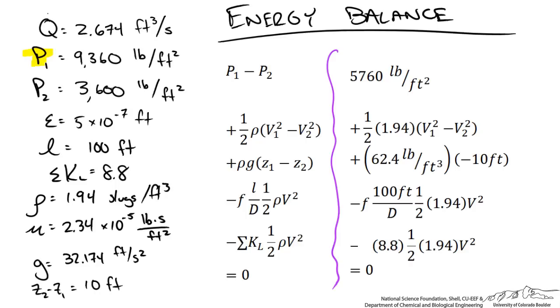Now when we think of this system, water's coming from a main water line into one we are building for the apartment complex, and eventually out of some type of faucet in the building. So the specified large diameter of the supply line is there to give us the impression that the velocity in the main line is much smaller than that in the line we are building. And so for the sake of the problem, we assume that the velocity in the city line, V1, is negligible. So V1 is much smaller than V2.